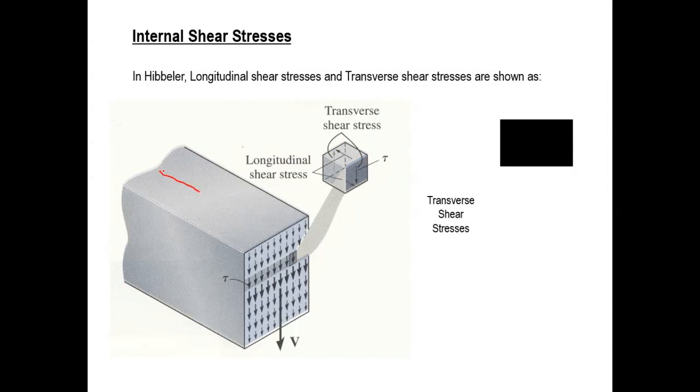So you can imagine that this direction is the axial direction. Also we call this the longitudinal direction. Longitudinal, axial, both of them the same. And then this plane, that's the y direction, I call this the transverse direction. So please listen carefully. The shearing stress on two sides here, a transverse side and a longitudinal side, develops on both of them, and you know what? Both of them are equal.